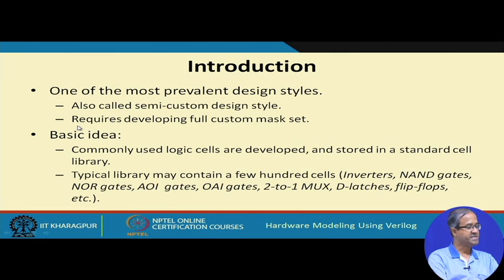But as I said, we have to go through all these steps of fabrication, which means we have to develop the full set of masks that are required for fabrication. The basic idea is that you use some simple logic cells which are very commonly used and store them in a library which is typically called the standard cell library.